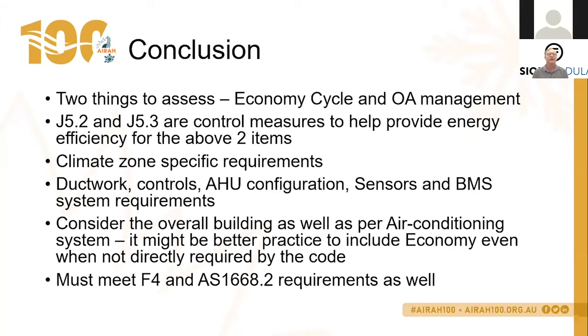So in that situation, you most definitely can control your air handler unit or fan coil unit and have it operate in economy mode if the outside air conditions are suitable, and you're needing to ensure that you're exhausting enough air through that kitchen exhaust system. So have a think about how you've designed your system and what's going to be most energy efficient. And yeah, I would definitely look at using economy cycle.